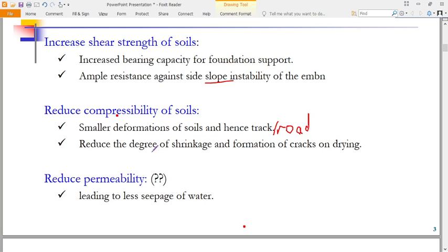So, if you want to achieve higher compaction, what do you use? Use a smaller lift, if that is for fine-grained soil. For coarse-grained soil, since you are vibrating, you can compact them in bigger lifts. So you can look at the normal soil.